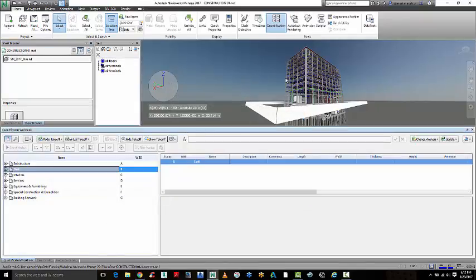And you can go through the model and do takeoffs, and it will extract that information about the length and the width and the volume and the weight of certain objects and load them into this workbook, which you can then export out as an XML or an Excel spreadsheet. So this is a really powerful tool that comes within Navisworks for doing quantity takeoffs.